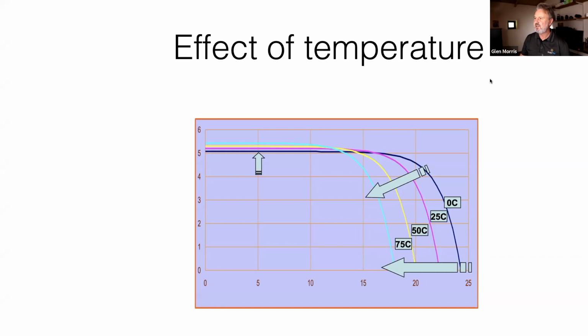John's asked, I live in the coldest town in Australia. Does this mean it's ideal for PV? I'm curious, John, what is the coldest town? I thought it was Perisher. I'm not sure if that's a town, but yes, the colder it is, the better performance you'll get instantaneously out of a PV system. But the problem is it's probably not going to be a lot of daylight sunlight hours. You're probably in a southern state, maybe Tasmania or somewhere, so your days will be shorter in winter. So actually, cold helps for instantaneous power, but we're generally more concerned about energy, which is the total amount of power times time. So that's probably not a big win for you.